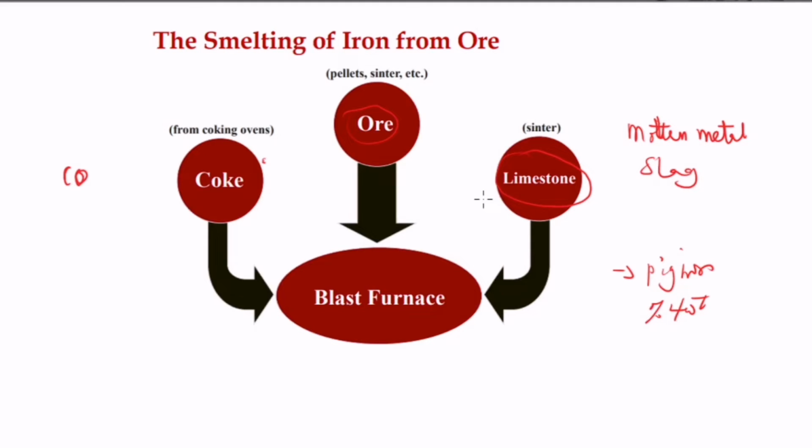We call it fluxes. Now when metal is smelted, the metal is separated from its impurities by melting, with the impurities forming a molten slag on top of the metal. Let me draw this. The top here is the slag, and this is the molten metal. Many of the impurities associated with the ore are difficult to melt, so they will not form a proper slag, which retards the smelting process.